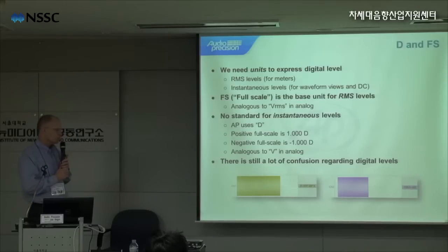So there's still a lot of confusion regarding digital levels. In English we use an expression called a gotcha, which means a customer phones in and he says, I calculated the level in the noise using your FFT, and it's wrong by 3 dB, 3.01 dB. And of course it's not wrong, it's because there's a different convention.